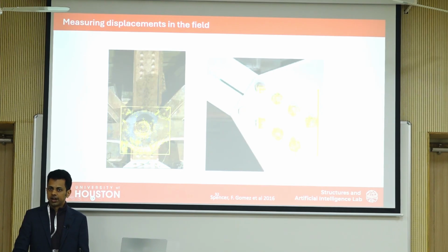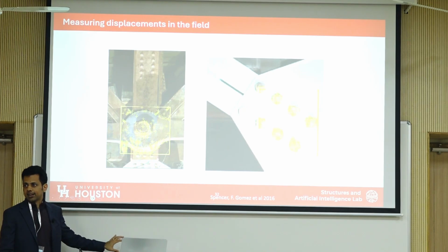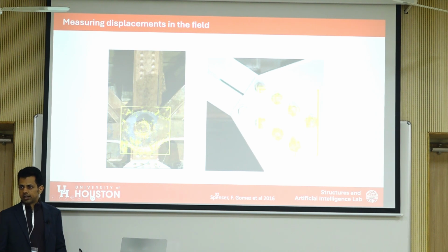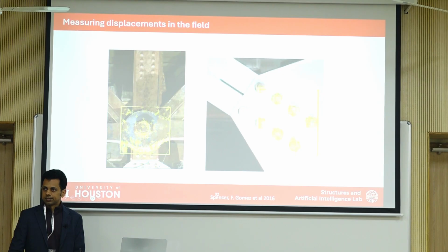Now, one thing you need to be careful of is that if you're trying to classify cracks based on severity, that classification shouldn't depend on the scale, right? Because if I take a close-up picture of a crack, it's going to look big, versus if I take it from there, it's going to look small. But it's the same crack, so it should have the same categorization.